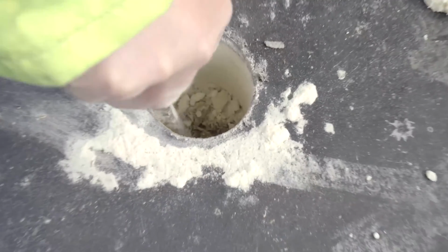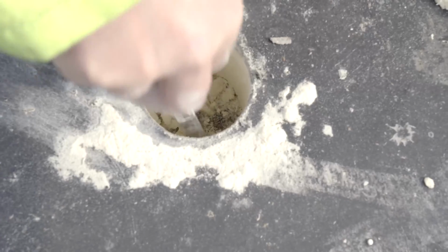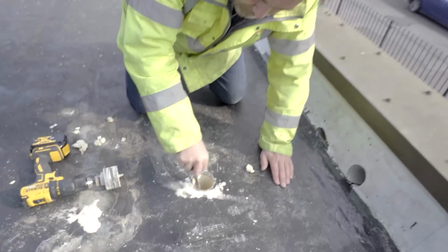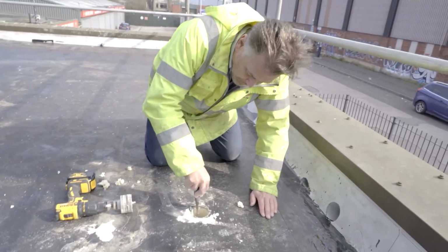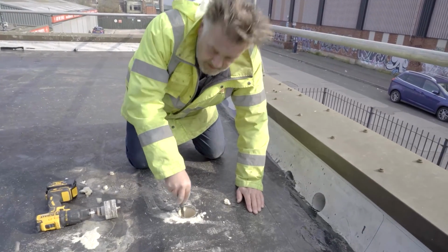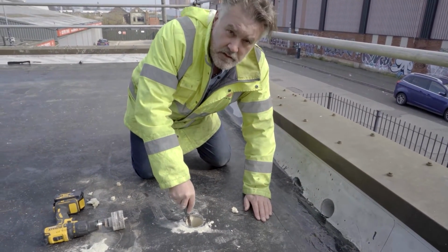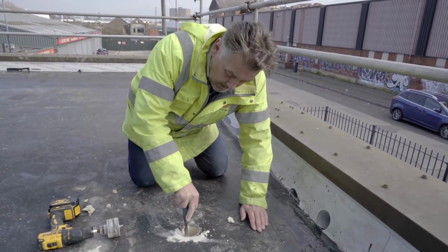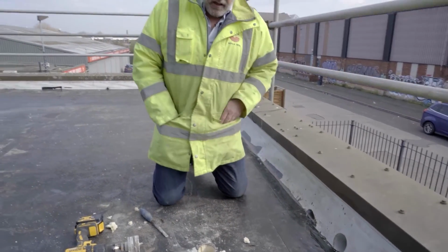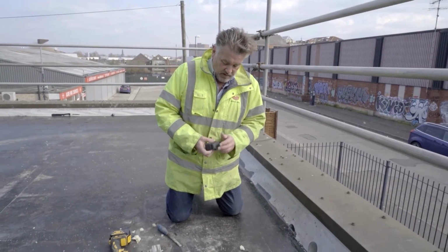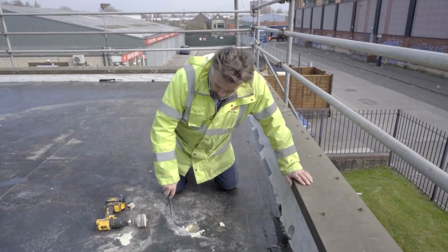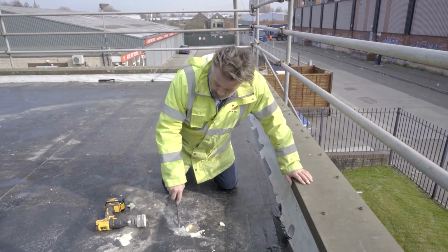Right, I can see that there's asphalt there. So originally this roof, when it was first built, had an asphalt roof on a concrete deck. People have since gone back. They've used the existing asphalt as a vapor barrier. There's no separate vapor barrier in place, and then there's PUR insulation, which looks like it's a good thickness. So I've learned from this that the roof's dry.